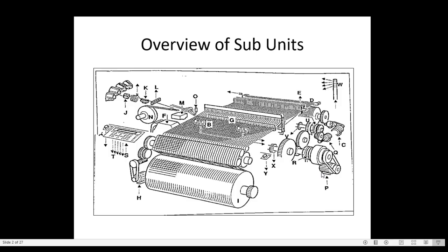After that we can see here the main motor. From main motor, here drive has gone to the clutch, we can see here the clutch. So here change of pulley we can do. So clutch engage and disengage is there here. When any warp stop motion is there, warp breakage is there, here clutch disengages. Motor runs, main shaft doesn't rotate because clutch has disengaged.